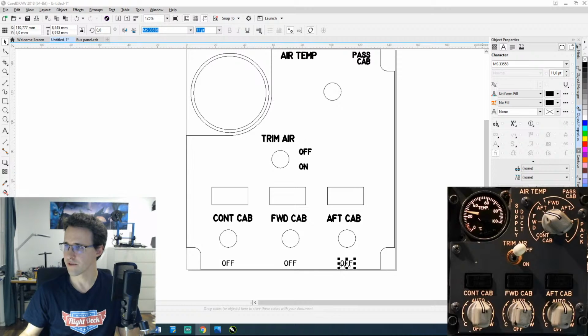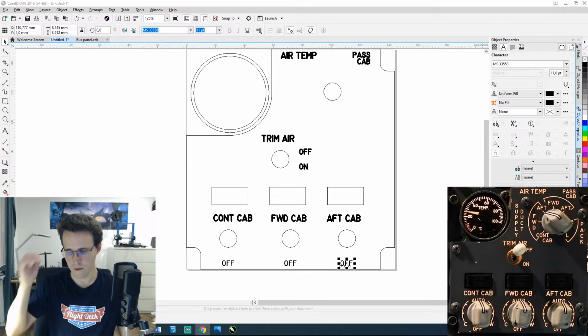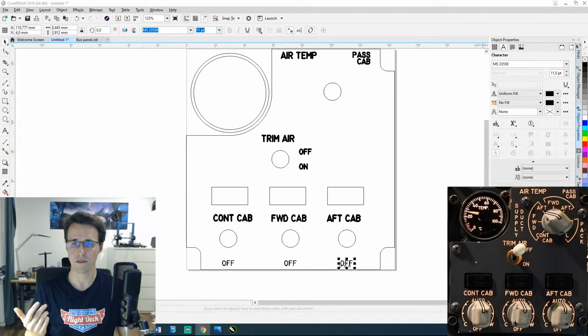So, Indian Aviator, thank you for sharing this input on engraving. I will stick to milling. Yes, there's no shame sticking to milling. I think laser engraving gives me some more opportunities, for example, producing faster, cutting out and so on, and going smaller. For gears, it was a huge change for me. I can now cut much smaller and finer gears than I was able on my CNC. Yes, but there are some more things you have to take into consideration when switching to laser.